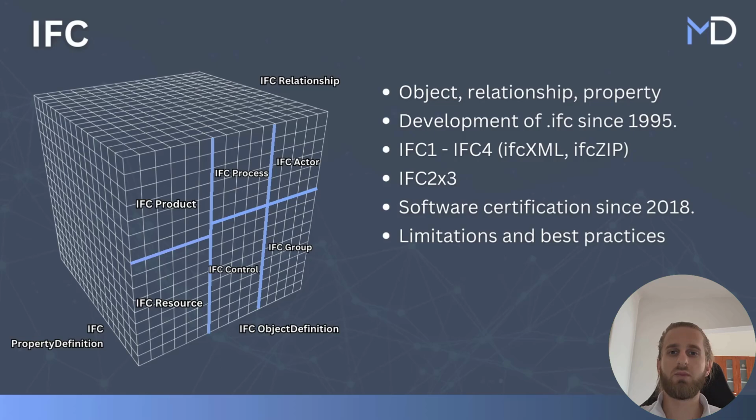So if you work in Allplan, in Allplan format. If you work in Revit, the Revit format, and so on. IFC should be your end product. It should be a product that you put in the common data environment where all the models are connected.